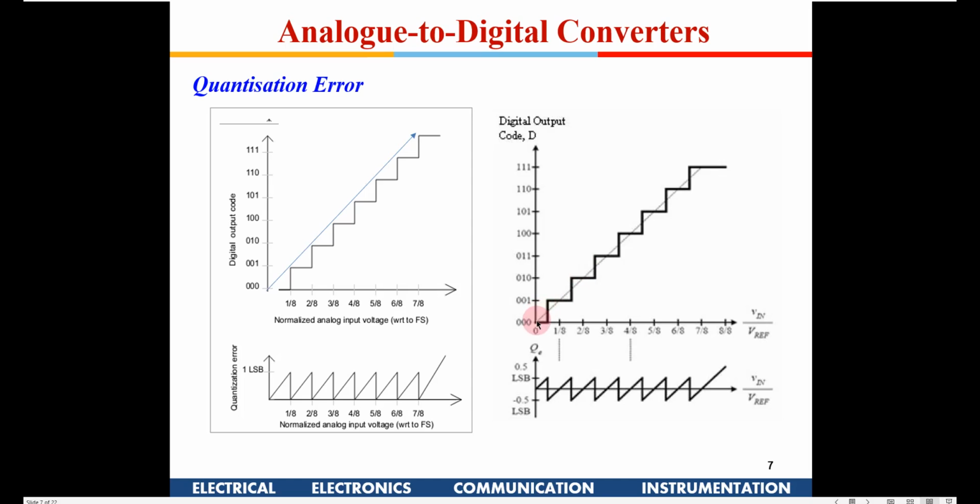But if you try to make an ADC graph like this, where this is the step size and I make the decision in between, if the signal is beyond this level, it will make a transition. So again, here is 0 error. Till here it makes a positive error, and here it makes a transition at this place itself.